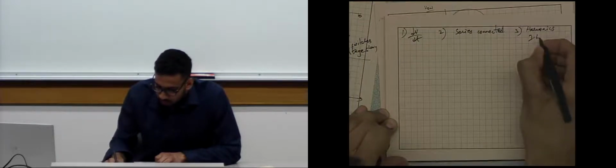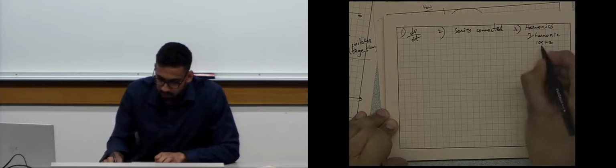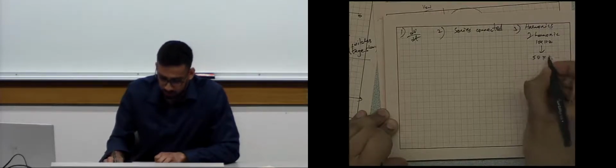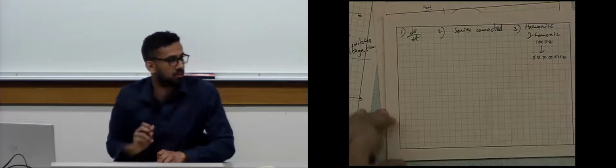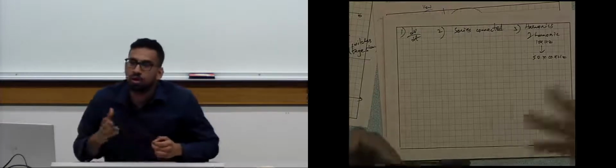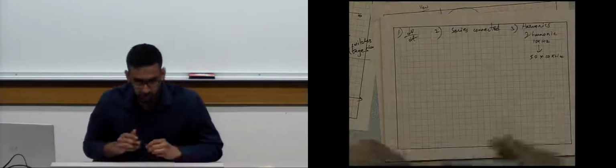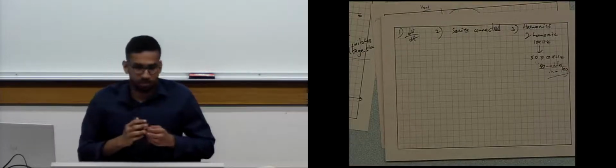So the first harmonic in case of MMCs, instead of being at 10 kilohertz for 10 kilohertz PWM, will be at 50 times 10 kilohertz, the first harmonic. So much purer sine wave in case of MMCs, if we have 50 modules in a leg. Okay. So that is a motivation to go to MMCs. Now we are all done with the motivation, and let's just dive into MMCs.